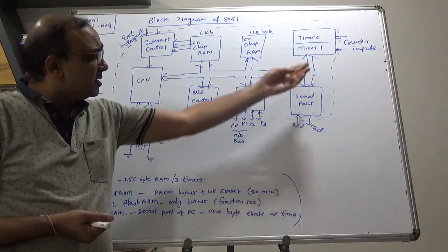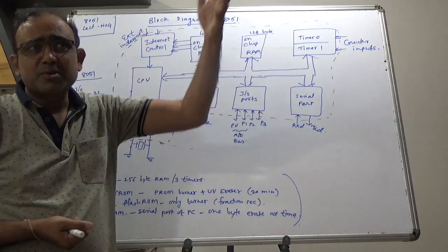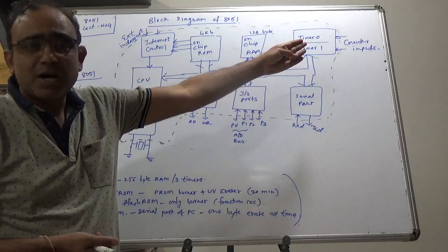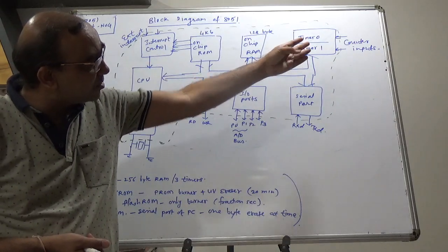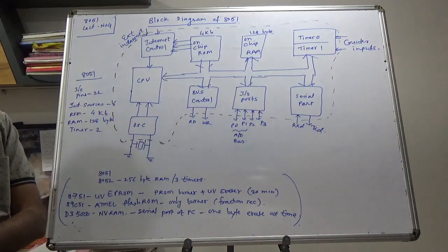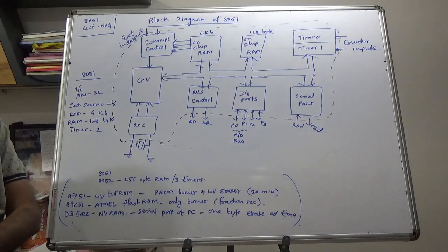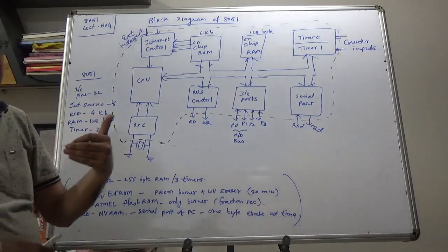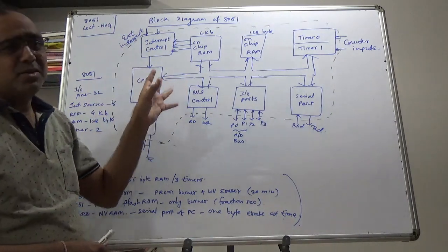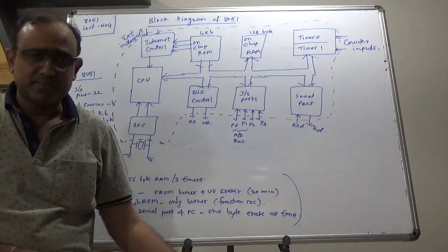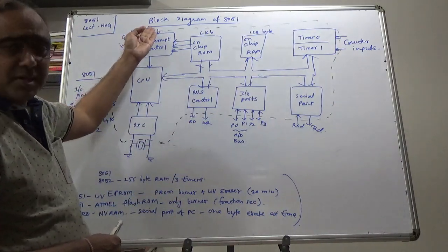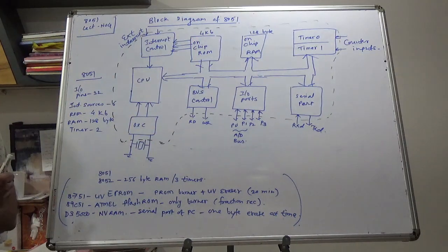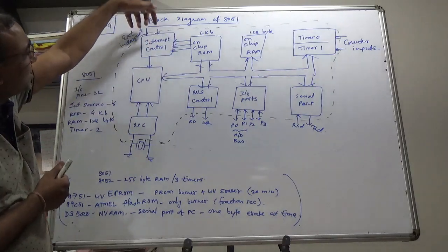Okay. You want to count some pulses. Suppose your project is to count how many persons are entering into a particular function. So you need some counter pulses, and those are given at the counter inputs. Sometimes you want to interrupt the microcontroller. Now we'll talk in much detail on the interrupt topic. Actually, interrupting means, see, the microcontroller is doing some task and you want the microcontroller to do another task. So how will you interrupt? So there may be some external interrupts, there may be some internal interrupts. We'll discuss in detail when we discuss the topic of interrupts. But these are the external interrupt pins here.